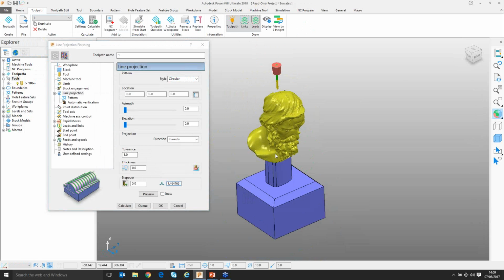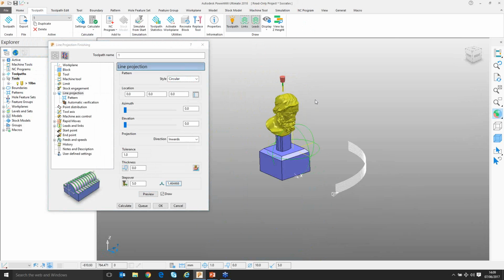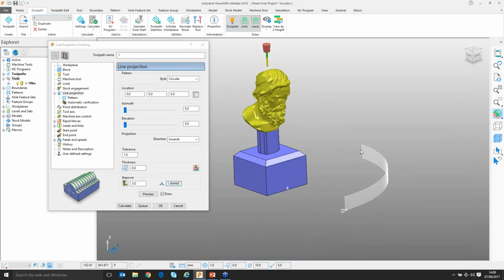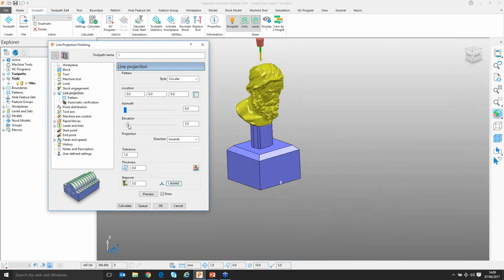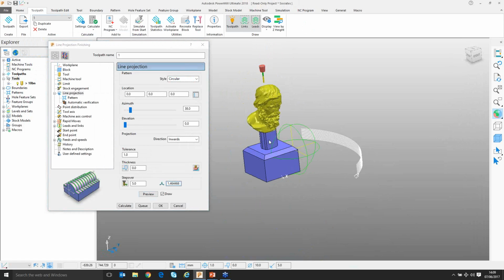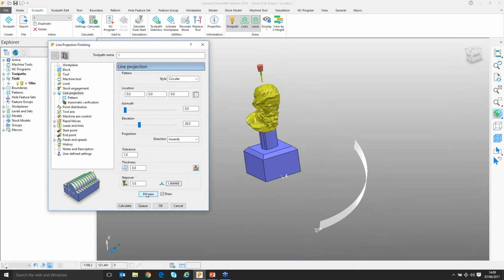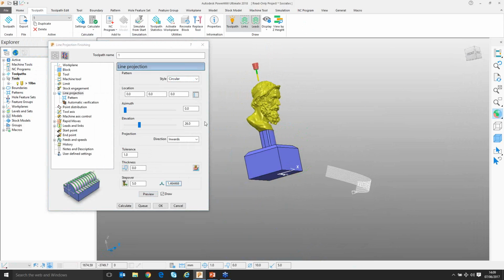Similar looking form pops up in that we've got an azimuth and an elevation angle. I can preview immediately, and this time what we see is that we now get part of a circle going around a theoretical line in space. I can control that line by dragging these values. I just preview again, you can see that I've dragged that around, maybe do the elevation, that would be more clear. You can see that we've started to drag that in various directions.